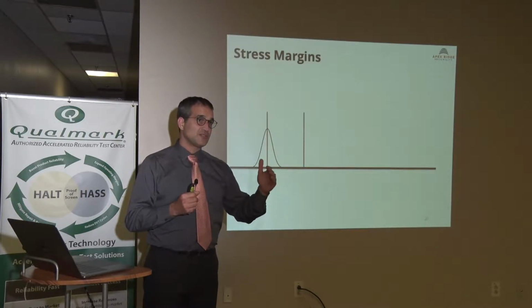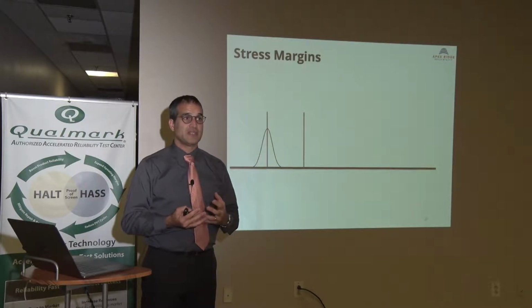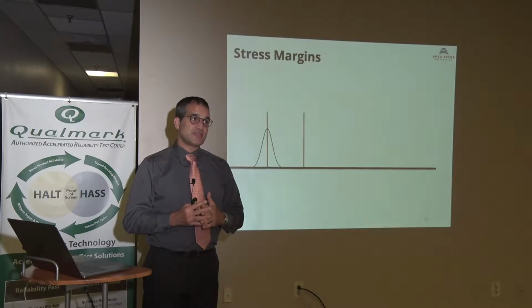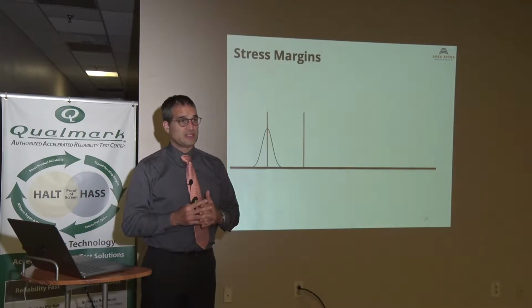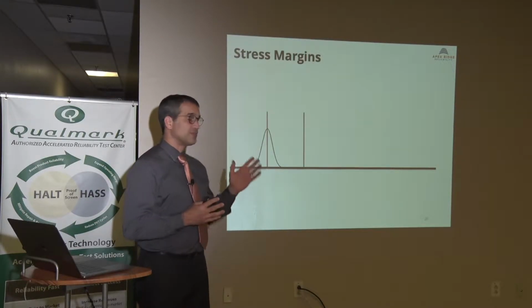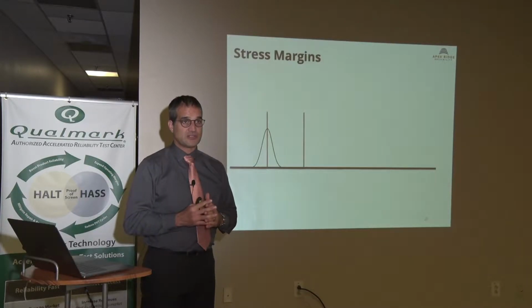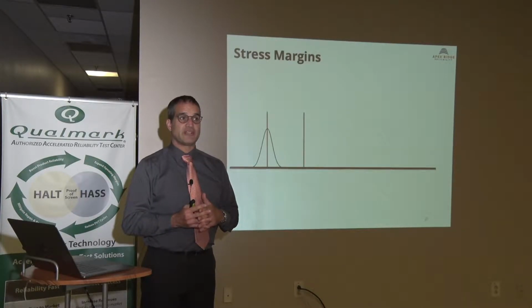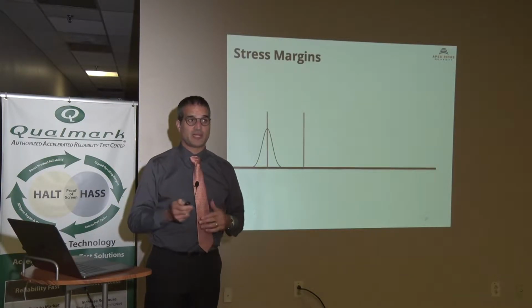And the response to an extreme stress should be somewhat similar product to product. So we're less concerned with sample size. But here, with use case 7, we are keeping that connection, so we do want higher sample sizes than we do with HALT testing. And that's for the simple reason that there is going to be a distribution. And if we do end up testing with the Superman unit, we're not going to find out the true relationship between the stresses and the performance of the general population.